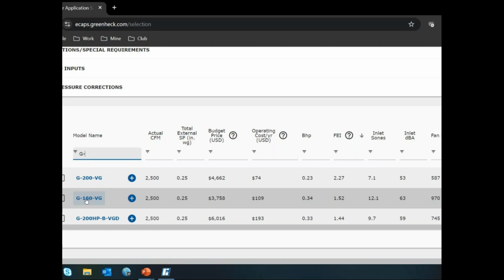Belt drive fans, I have to maintain them. I have to tension the belts, replace belts. I got to grease bearings. So if I can get that in a direct drive fan where I don't have to put that effort in to maintain the investment I made, awesome. Now, I will say this right off the bat: belt drives will never go away. Belt drive fans have their niches where they are the right selection.